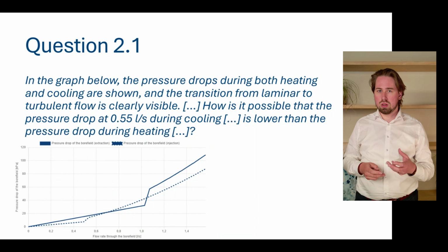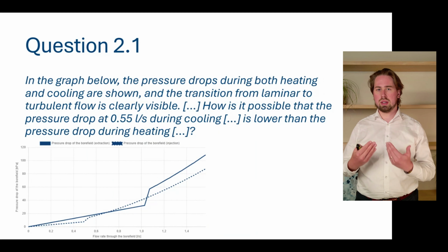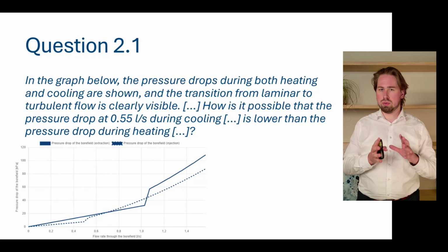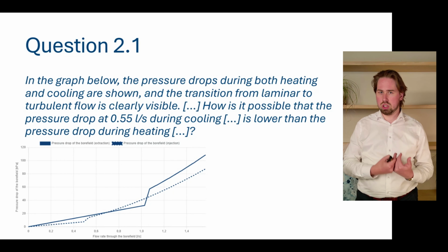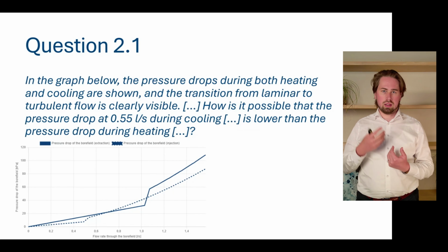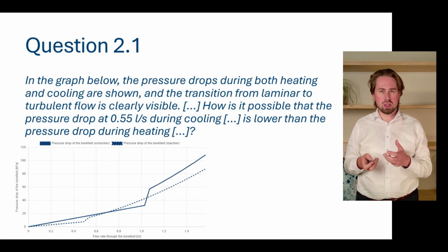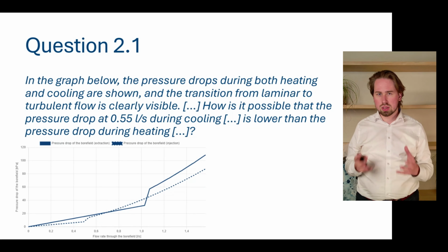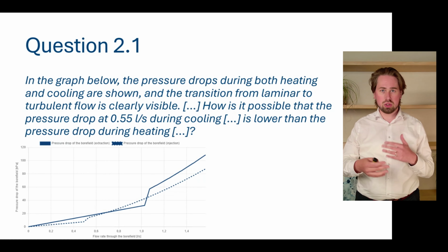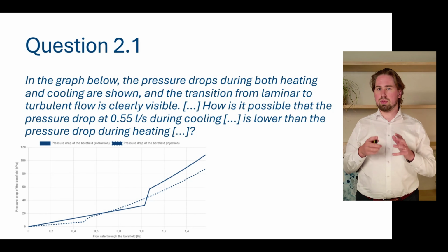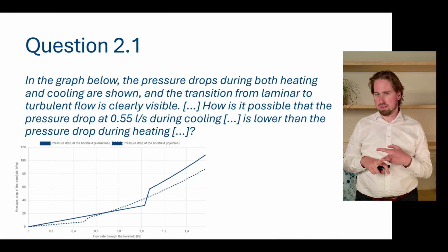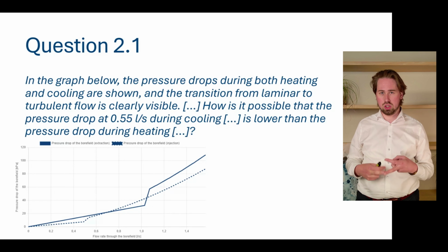In the second chapter, we deepened our insights in the pressure drop and took a look at how this pressure drop is actually used in the hydraulic design of bore fields, in particular, and especially in GHE2. Because we discussed in the last part, when we're talking about the design of bore fields using newer state-of-the-art methods, that the viscosity and the Reynolds number is no longer constant in the simulation. It varies with temperature, so it varies over time. And this means that if we're talking about pressure drop, well, we have to define at which temperature and at which flow rate, because also the flow rate is no longer constant in GHE2.